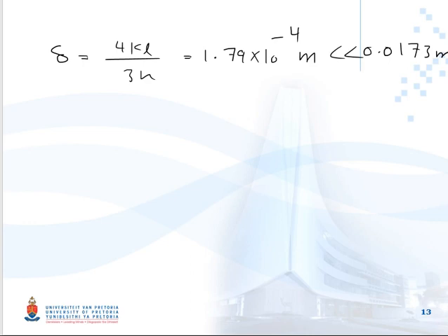You again write the correlation. You put those numbers that you read from the table into the correlation. You find the Reynolds. You double check if your first assumption was correct. If it was correct, you continue with calculating h, and everything else will go the same as the example that I solved. There are other ways to sort it out as well, because you can see that it can be added to the heat exchanger concept, and you can mix different concepts into it. But don't panic. It's very simple. Just follow the same procedure and everything will be fine.